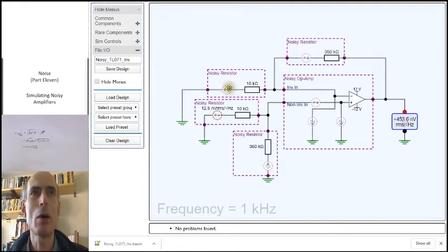So they are now a bigger contribution to the output noise voltage than the equivalent input noise of the amplifier itself. The feedback resistor, only 76. The noisy resistor down here, another 76. Fairly negligible compared to the two input resistors, which at 10k are providing the majority of the noise.